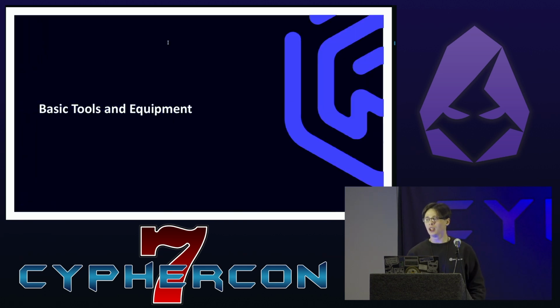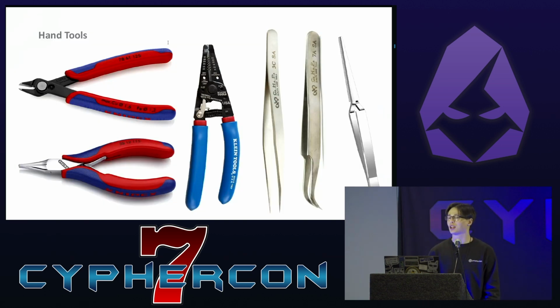So starting off with basic tools and equipment, these are going to be useful anytime you're working with hardware, no matter what the device is. These are going to come up time and time again. So your hand tools are going to be a good place to start. The nippers in the top left, also called flush cutters, diagonal cutters, a million and one names. Those are going to be your best friend. And honestly, for some finer gauge wires, you'll just end up using those as a wire stripper. You won't even bother grabbing wire stripper half the time for them. So getting a nice pair of nippers is really great.